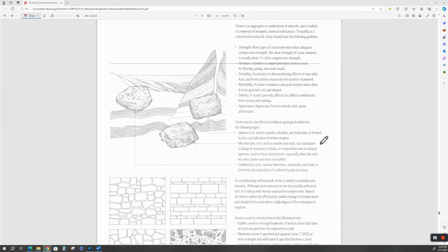If you're going to use stone as a structural wall, you're going to need a good stonemason, somebody who actually knows what they're doing. By the time that you pay for a natural stone wall that's structural, you probably could have gotten a reinforced CMU wall of some sort with a brick veneer than stone.